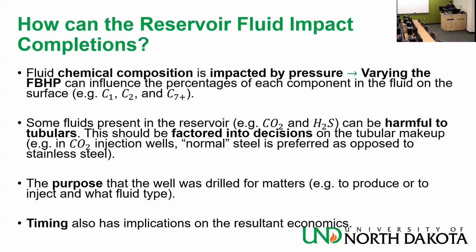Well, was that reservoir water flooded? For example, the Bakken formation. Bakken is a little bit different because Bakken is shale, so you really don't inject much into shale. There is not much you can do to change the temperature other than when you inject some fluid to fracture, maybe the fluid you inject is cold, but it's not going to change the temperature for the long term. It's going to be for very little. So basically, it's all about the pressure. There is not much you can do for the thermal unless you are using a thermal EOR method.